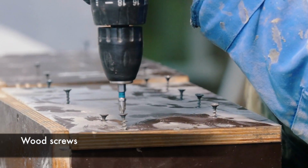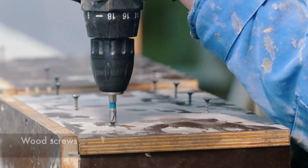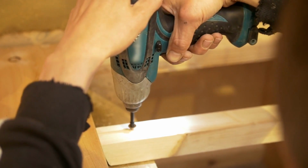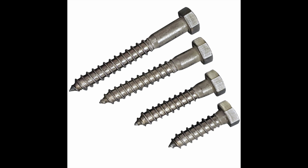Wood screws are made in a variety of diameters and lengths. When using larger sizes, pilot holes are drilled to avoid splitting the wood. Lag screws are large wood screws that are used to fasten heavy objects to the wood. Heads are either square or hexagonal.